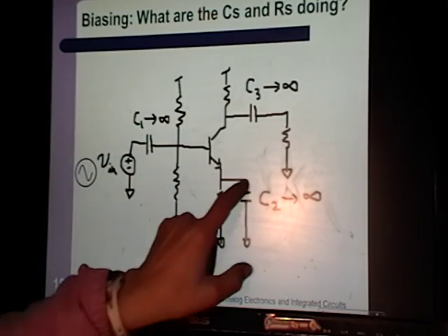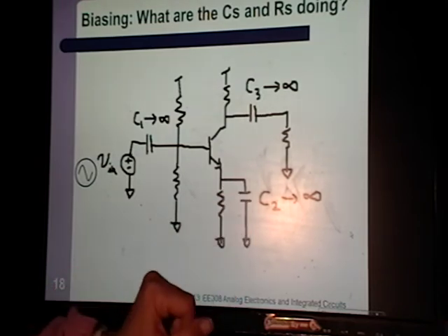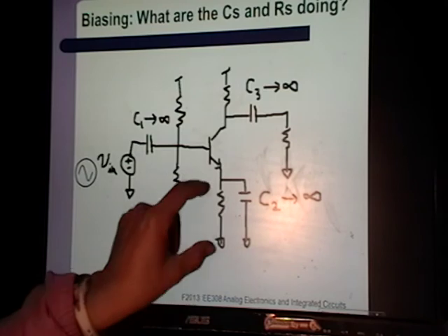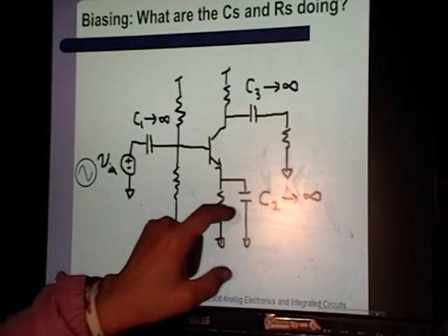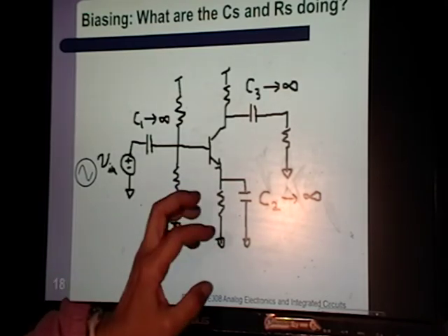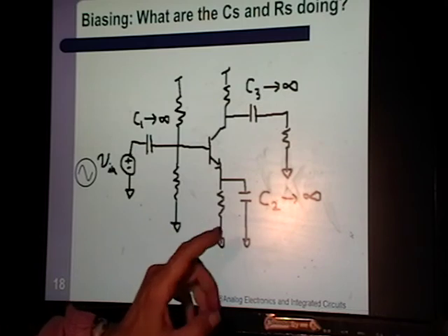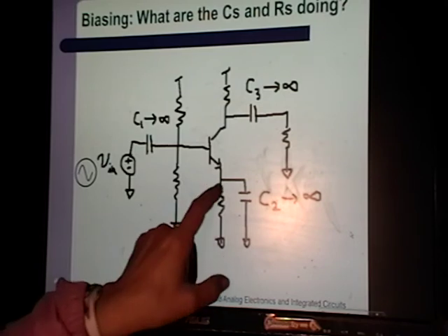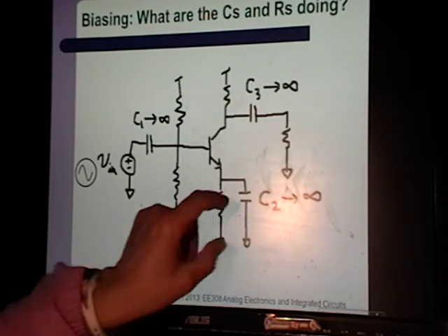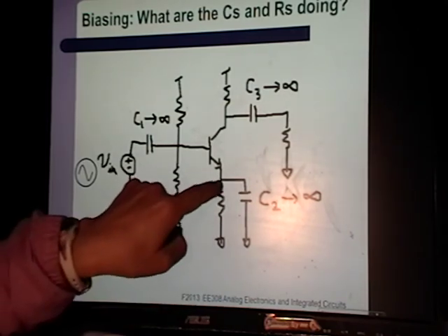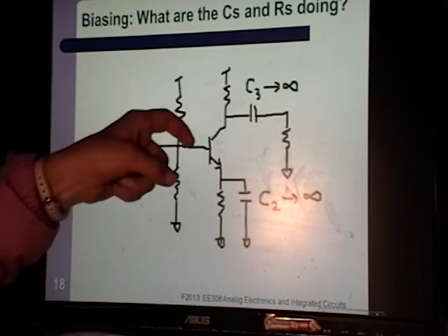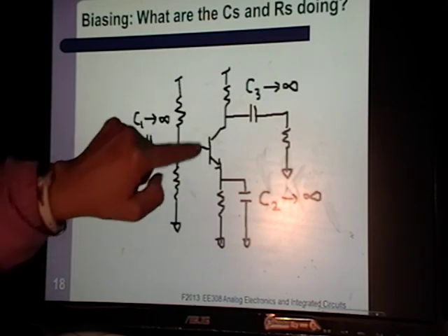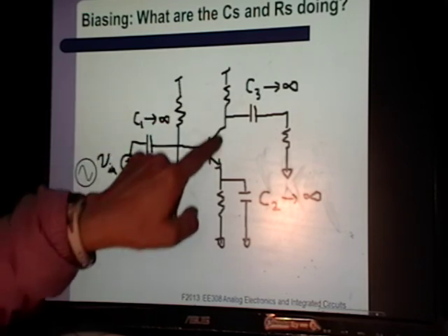So what you can do is use this capacitor right here. It's called a bypass capacitor, and you put it in parallel. A bypass capacitor is connected to any node that you don't want to move. So let's see how it keeps this node from moving. The way it does it is, when you change this input here, you get a current change through your transistor.